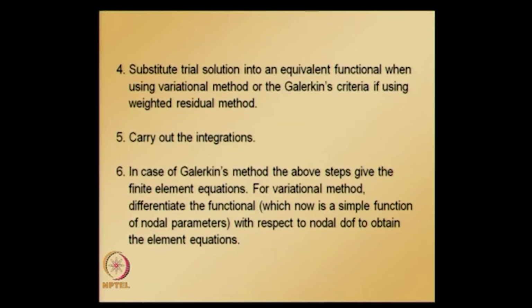Now for an isoparametric element, it is usually difficult to express element equations in an explicit form because of the need to integrate complicated functions. Explicit expressions are possible only if we can carry out integrations accurately without adopting any numerical techniques, but sometimes the integrand becomes complicated and we need to adopt numerical integration. So we will also be looking at numerical integration schemes. One of them is the Gaussian numerical integration procedure. That also we will be looking at as a part of the study of these higher order elements.